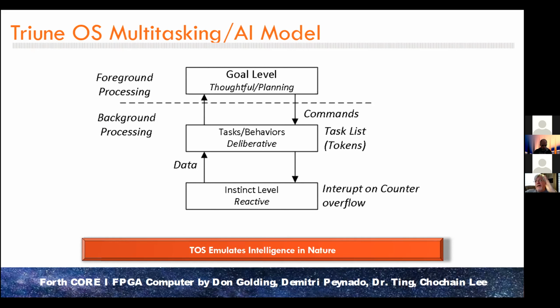You want to have high priority tasks in the front and low priority in the back. The back might be hold compass heading to 360 degrees. If it sees your behaviors in front of those, it might be, I got a double whisker hit, 2 sensors in the front see something, and it has some behavior for doing that.